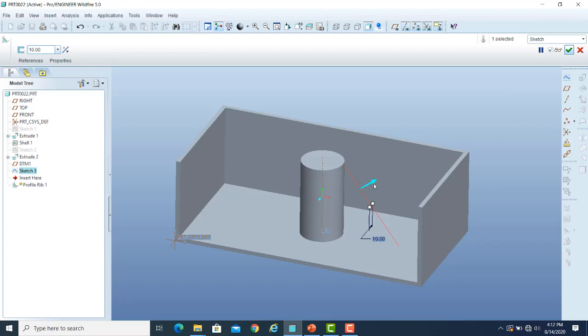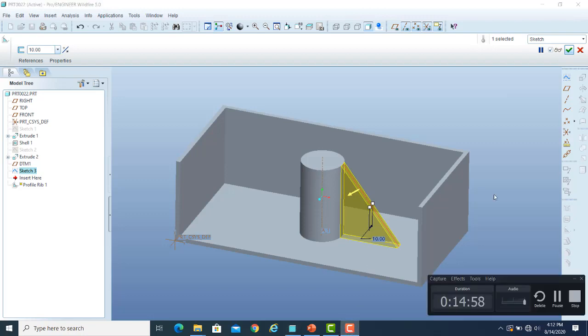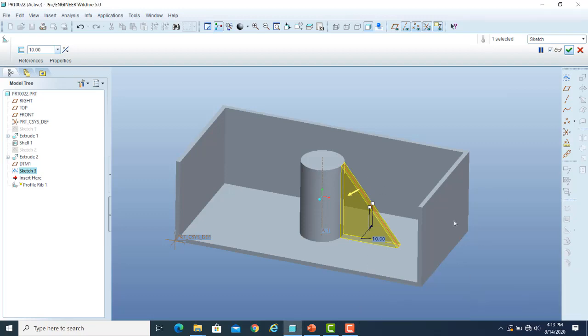So generation में आपके पास इस साइड पर अगर आप देखें, so you have an open region, so rib cannot be created. इसको अगर मैं दूसरी साइड की तरफ कर दूँ, so now it is creating that rib feature. So you must take care of that direction. Ribs will only be generated if it has a close boundary on that particular side.